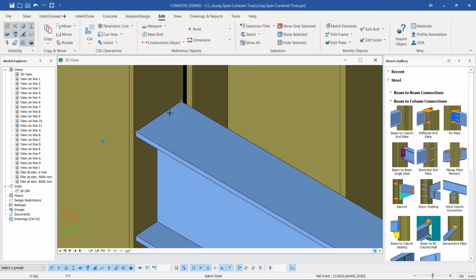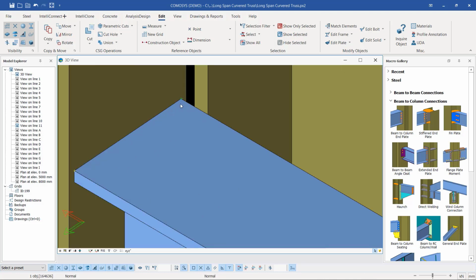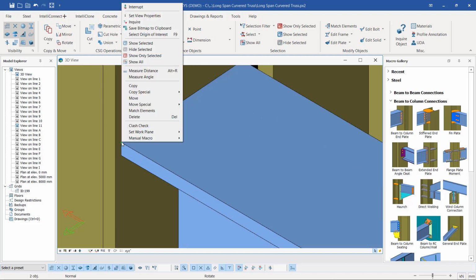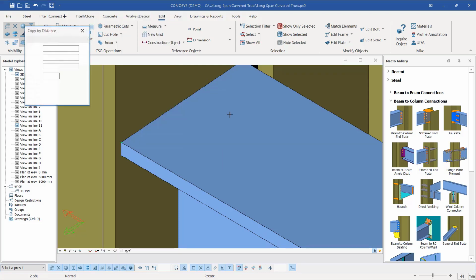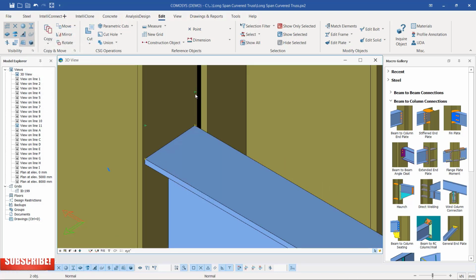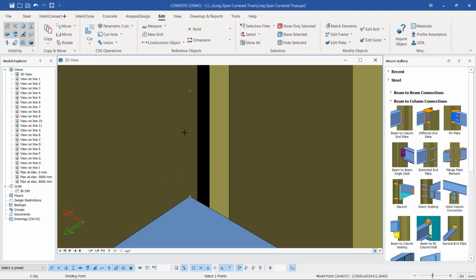So what I'm going to do once again, I'm going to offset these points upward by some millimeters. So let me just select that and press Control, and select on this and press Control. Then I'll right click and come to Spatial Copy, and I'll pick on Linear. So I want to offset this upward by a few millimeters right there. So let me just feed in here 50. 50 will be okay. Let me just type 50 there. So if I click 50, I'll be able to see I have my plate slightly up, but the offset is somehow extreme, and I just want to minimize the gap.